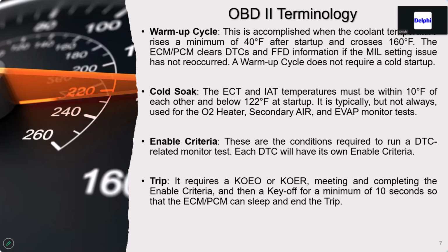It requires a key off and key on, engine off, where you might just turn it on and it might do a TPS circuit check. It might do a coolant sensor check. And after a period of time, it judges it pass or fail. But a lot of your other tests, you have to have key on engine running. You have to meet certain criteria. And once you meet that criteria, then that's considered part of a trip.